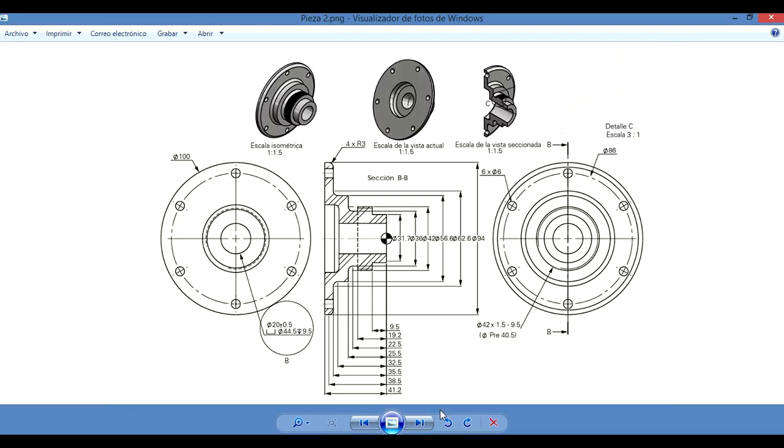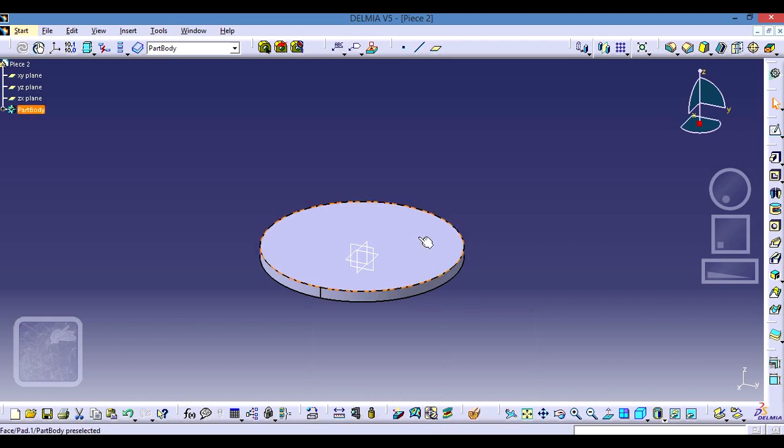We continue, guys, to the second level, that is this one. For this level, see the arrow of my mouse, please. We can see the diameter is 56.6. We're gonna go back here and we're gonna click on this face, because the next level is about this face.